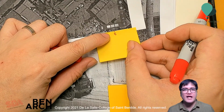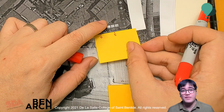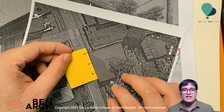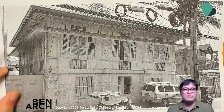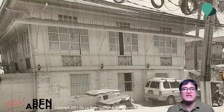Using a post-it or any small piece of paper with a straight edge, replicate the 5 meter scale bar and start measuring the roof edge. In this case, the measurement of the roof front edge is 14 meters.